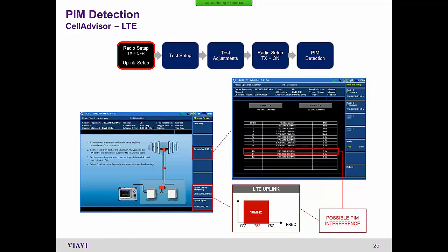All right, our PIM detection feature, which by the way is available inside the Spectrum Analyzer, so you'll notice here it says Mode Spectrum Analyzer at the top of this screen. If you were connecting to an RF port, this would be the screen you would go to. Essentially, in the analyzer, you go into the Spectrum Analyzer and hit the measurement button, and one of the measurements available, I think you have to hit measure then more, is PIM detection.